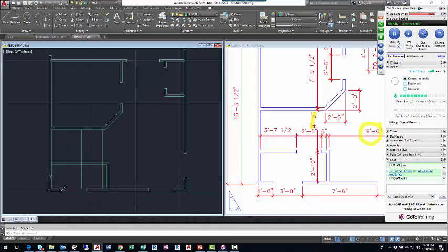Now I'll use the trim command to clean up or create the door opening and hollow out the walls basically. So trim, enter, make the door opening first, remove the cutting edges, the excess lines. Missed it. Got it. And then at the base of the vertical wall, I'll trim out the horizontal wall line.